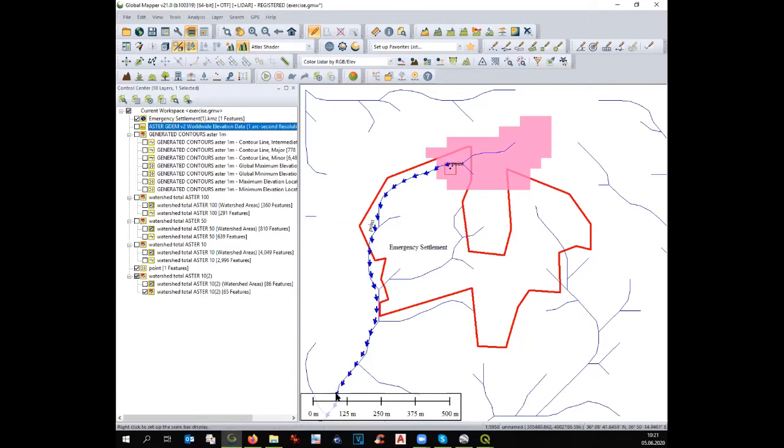And that means if the rainfall falls at this point, the water will go from this side. Exactly. And that's why it is important, because now we have, let's say, the main drainage lines of your site. It means, first, you don't have to put tents here along the drainage. And if you do, let's say, a concrete drainage or an improved drainage system, you should try to use the natural depression. It means you should try to put the drainage around here and here and here, because you don't want to dig so much.